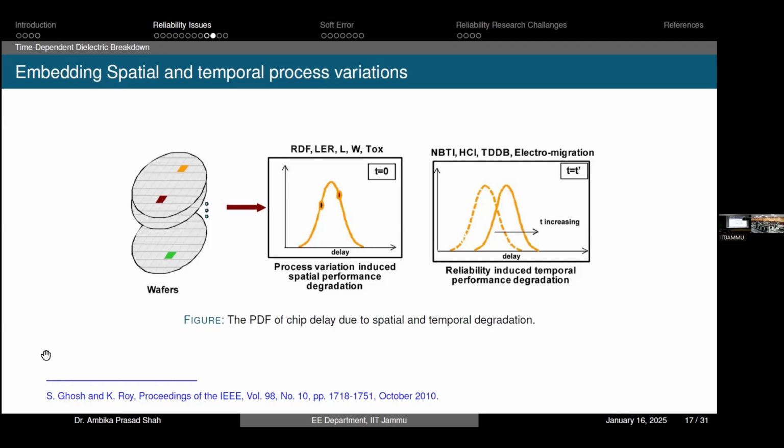Yeah, there are different mechanism schemes. For that, just read one of my transaction papers, where I have mitigated the impact of NBTI after designing the circuit. Body biasing could be one of the techniques that can help us, because body biasing helps us change the threshold voltage. If the threshold voltage is increasing and you apply the reverse body voltage, definitely that will compensate that change.